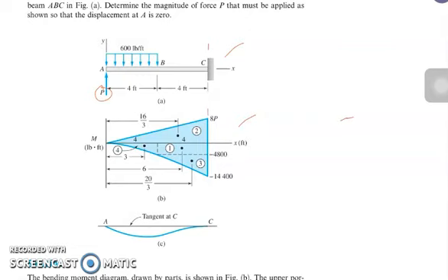So for our bending moment diagram, we start with our P, the concentrated load. So P times the distance from point A towards point C, which is our reference point. So this will be 8P. Since this is a concentrated load, you will have triangular loading. Then we have 600 pounds per foot. This is a uniformly distributed load, so this will be downward.